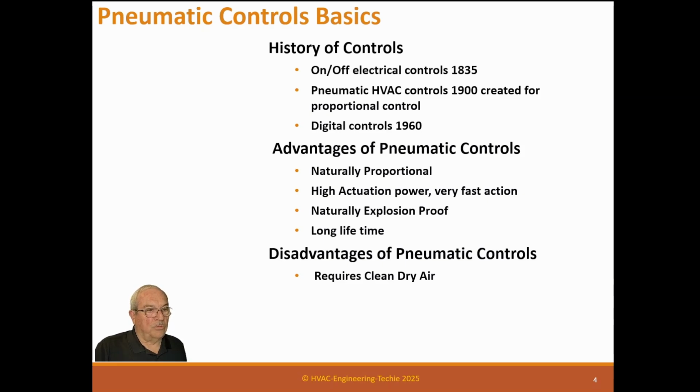We pumped the system full of water, but we drained it, and then we put nitrogen in it to dry it all out. And I said, well, I hate to tell you this, but you've just damaged and ruined every thermostat, all 385 of them. It's a hotel, and they said, what do you mean? I said, you've got to buy new thermostats. These cannot be fixed because you damaged them with water. You cannot have water in the system. That was a bad day for that operator, but it's the truth.